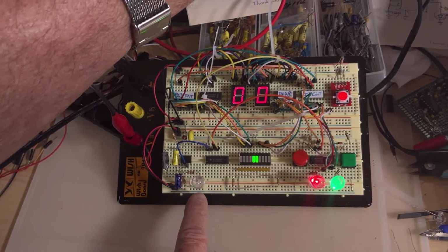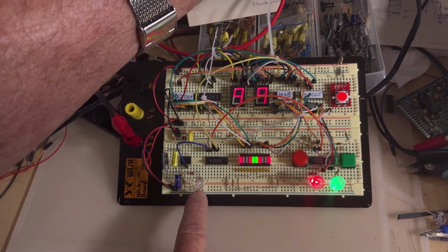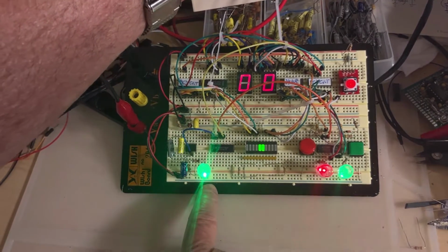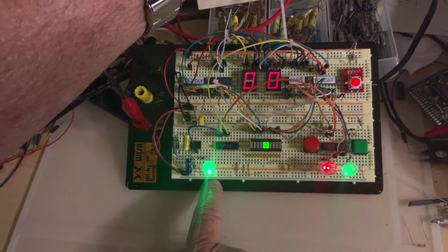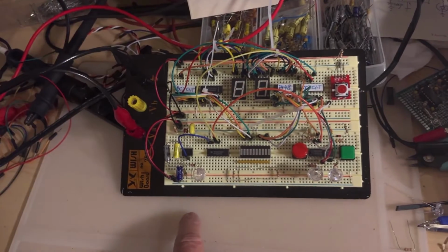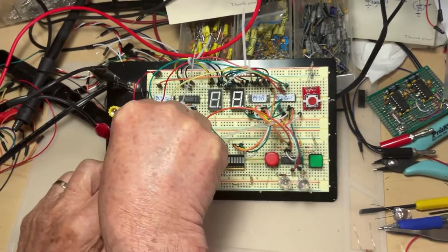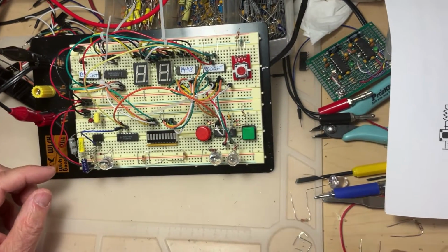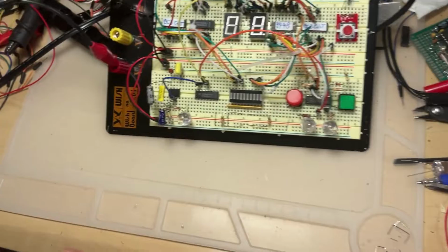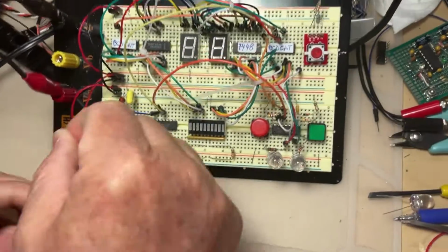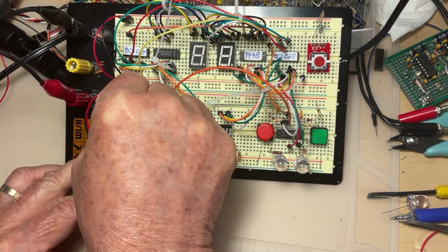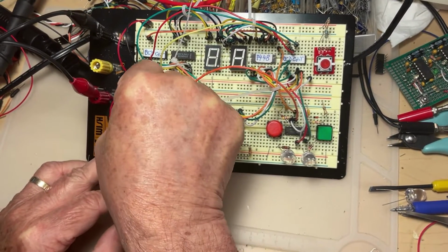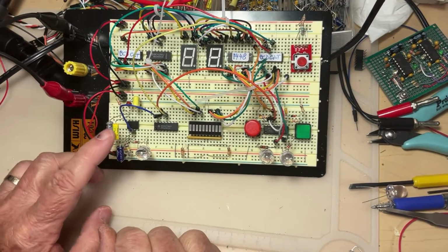Ah, you want to make it very short. You don't want it to stay that long at 0. No big deal. You put the power off. You remove this 220 kilo ohm resistor, and you put a much shorter value, like this one, 22 kilo ohms. So it's going to be 10 times shorter than before.